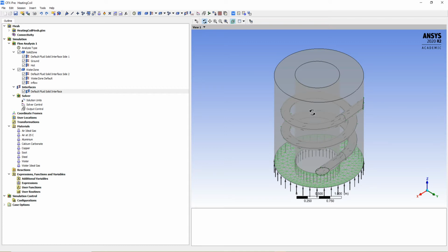So at an opening boundary condition we are going to set up a temperature for the fluid that enters through the boundary. Okay, so in this case it's useful to base this temperature of the fluid on the fluid temperature at the outlet, since you expect the fluid to be flowing mostly out through this opening.